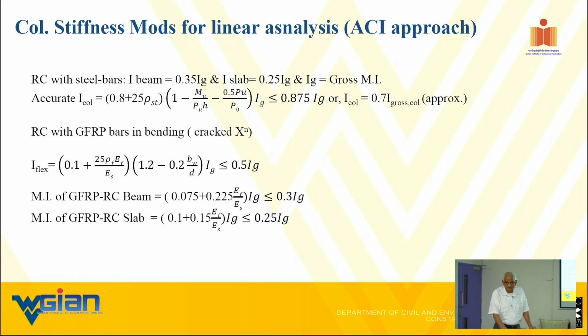Not a whole lot, really, 14 inches from bottom to the top. It becomes one heck of a lot of a number when you multiply the P times delta, right? Delta is only 14 inches, but the P is a zillion tons. That makes it drift more. The drift due to P delta can be higher than just due to the wind as a first order analysis. So that gives you a perspective.